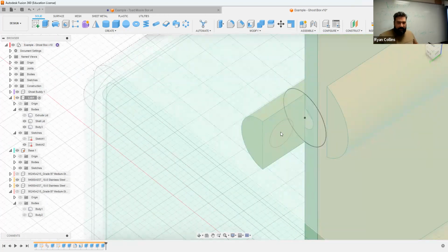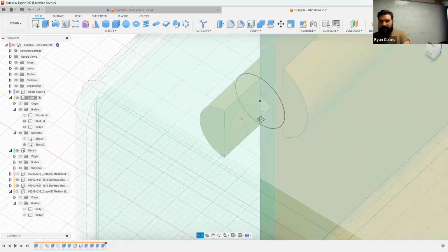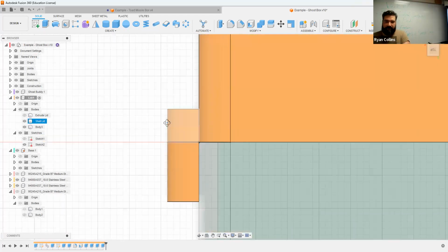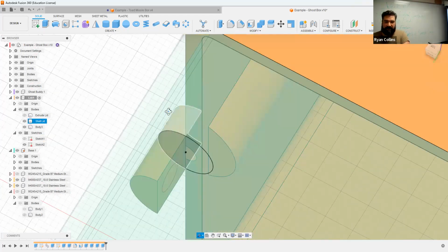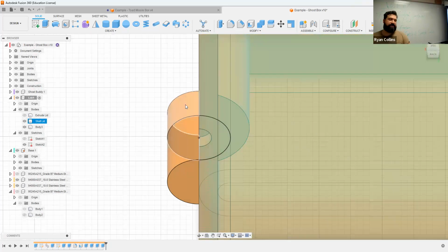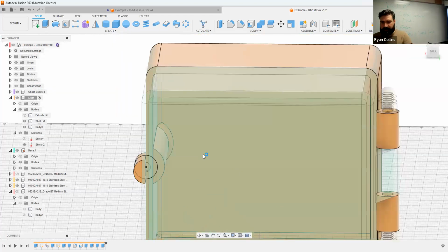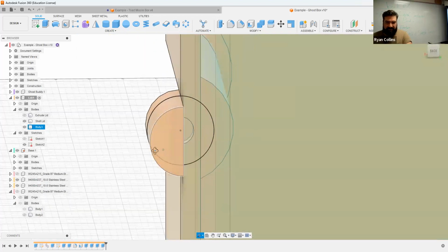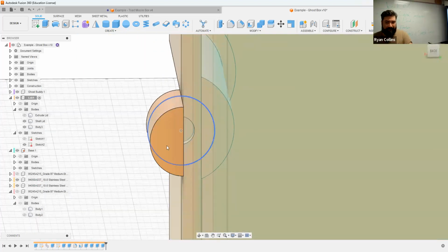So realistically, that's there. I can use that bump as a deleting tool, but the thing is it's kind of really thick there. You're going to have trouble working with that. So it might be best, with something like this, to not use a round tool. Maybe use something that is rectangular that you don't have to adjust too much. Or with this one, I can always just trim some chunks away from it. How I could do that, oops, sorry, I lost where I was orbiting from. How I could do that, pretty straightforward.